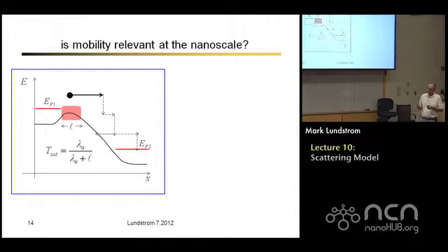You can look at different materials and get high mobility. You can do things like that. You can look at quantum confinement and see what that might do for you. But mobility is always, it's a concept. If you understand transport theory, you say, you shouldn't be talking about mobility at these length scales, when electric fields vary so rapidly. It's not a well-defined concept. But yet, it always seemed to steer people in the right direction. If you work on mobility, the performance of your nanoscale device improves, right?